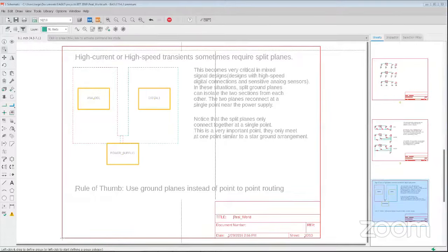So you can length match any net in your design. You just have to enter a length to match to. That's very easy. When you click on the meander icon, in the command line, type in what length you want it to match to, and then it'll insert the meanders. Also, if you're using differential pairs, it will give you the value of the primary, and also a percentage of how much they're matching between each other. That's only working on differential pairs.